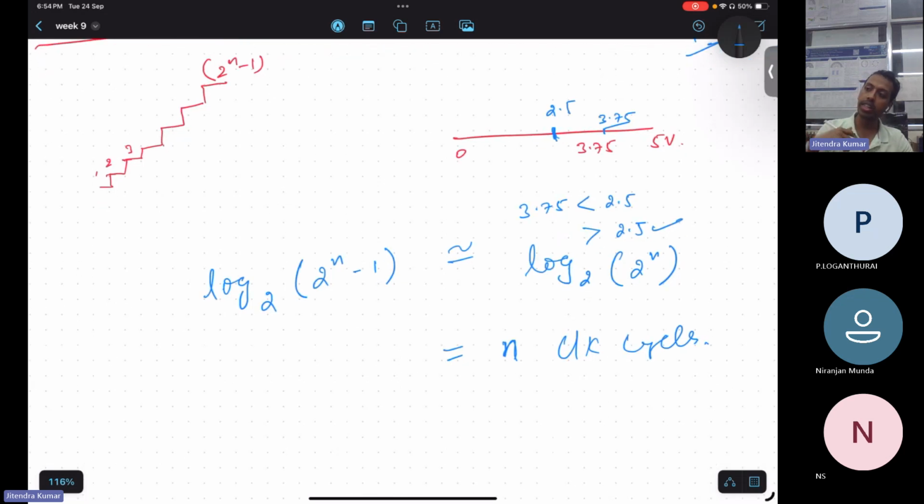So in the linear ramp type it was taking 2 raised to power n clock cycles. It has been reduced to n clock cycles in successive approximation. It is not doing a bigger task; it is just approximating with the help of the binary search algorithm. So did you get the idea behind the successive approximation voltmeter? Any doubt in this?